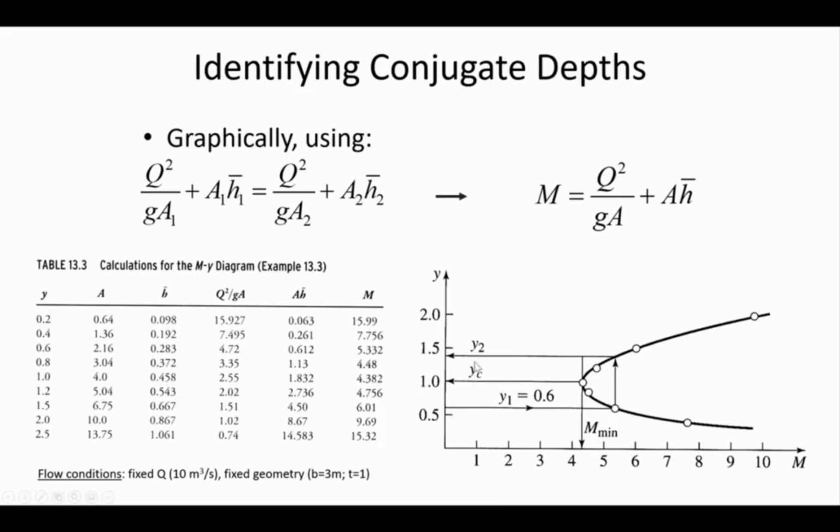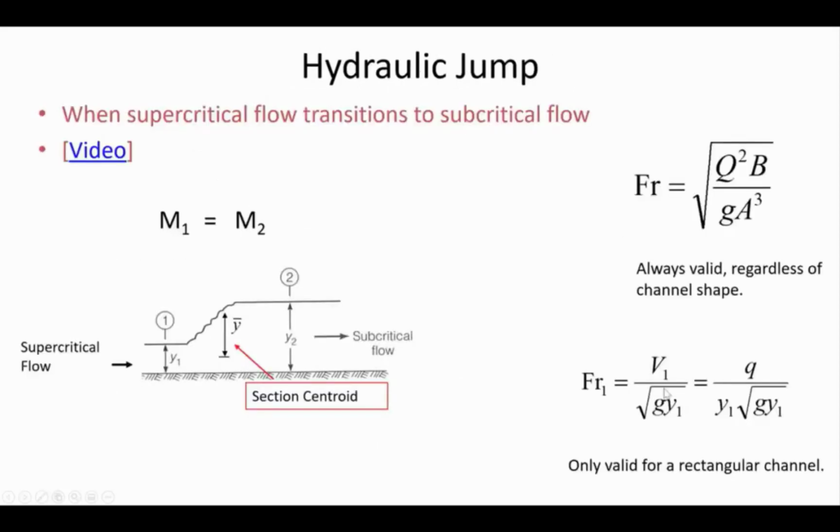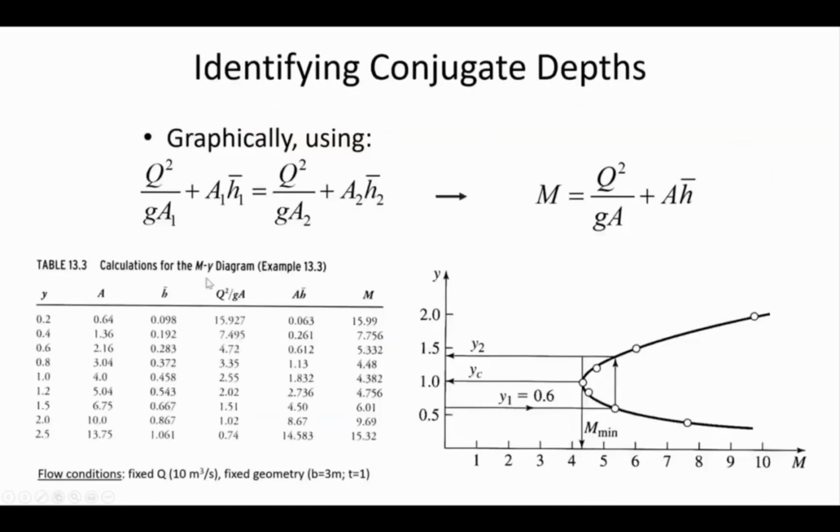The y1 and the y2, the difference in the upstream and the downstream depth, is how high the hydraulic jump is going. So look, there's y1 and y2. So there's a delta z between them, the change in elevation between upstream and downstream. So the change in elevation is the gap between the two legs of that momentum depth diagram.